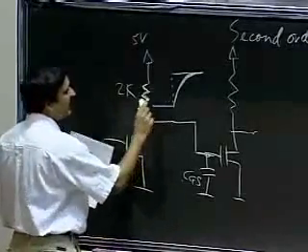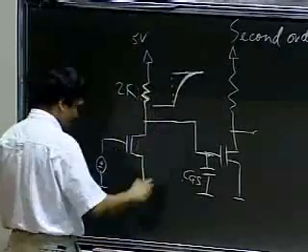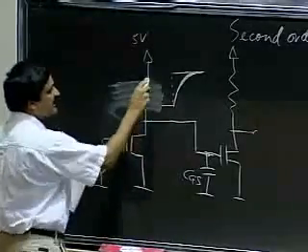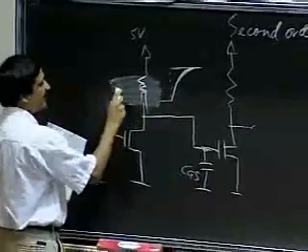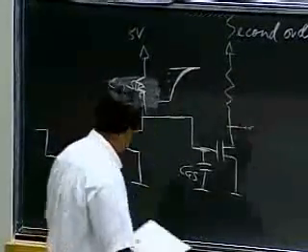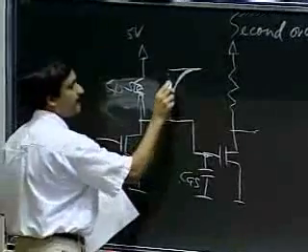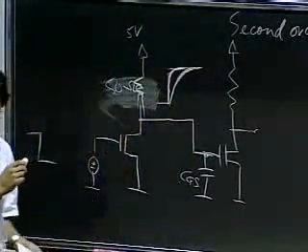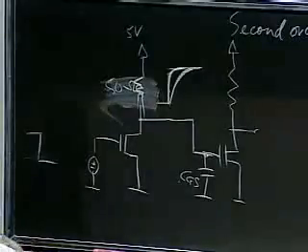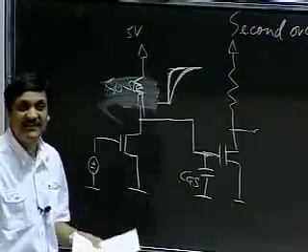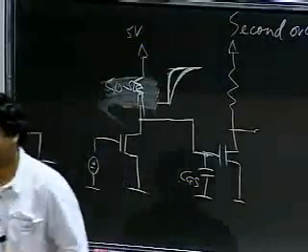So what I'll do is knock this sucker out and stick in a new resistance that's, say, 50 ohms, a much smaller resistance. Okay? That should speed things up, right? That should make things go much faster because this is a smaller time constant because R is smaller. Correct? Okay, let's go do it. And let's see if we get what we expect.